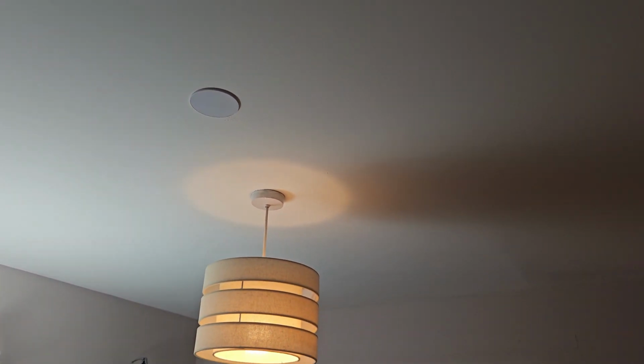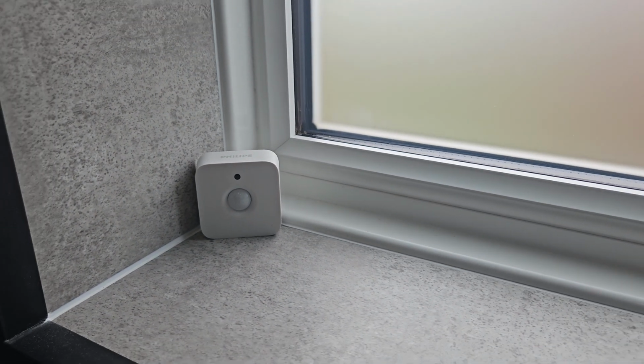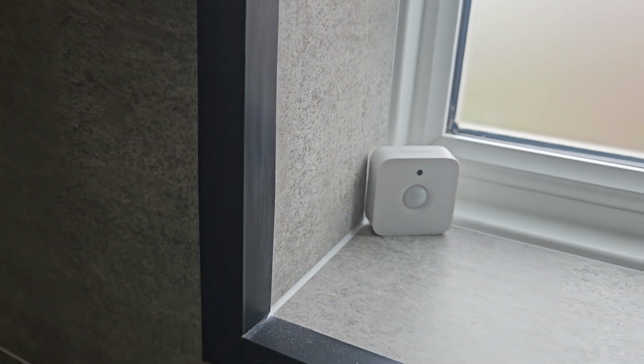Now, you will have noticed that I have said presence sensor and not motion sensor. Now, these are two different products, and a presence sensor is more reliable than a motion sensor. It is also more expensive, not by much, and it is definitely worth it due to the reliability that it offers. Now, motion sensors use passive infrared, so they're normally known as PIR sensors, and this works by detecting the infrared radiation that is given off by body heat. Now, the problem with this is that in environments that are smoky or dusty or have a really high temperature, passive infrared sensors can start to fail.